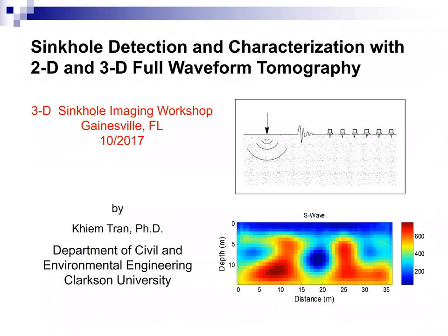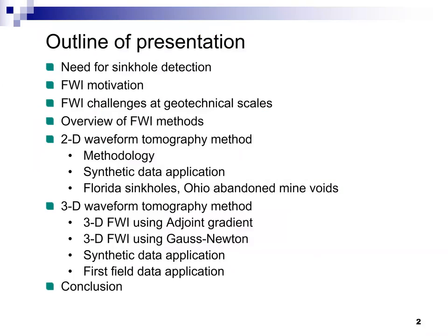Are we allowed to ask a question or two? Yes, sir. Please interrupt if you have a question. I'm going to be asking you if you have water in there in a bit. You have shear and compression, shear and P wave. For an air-filled void, we have a P wave of about 300 meters per second. For a water-filled void, we have 1500 meters per second.